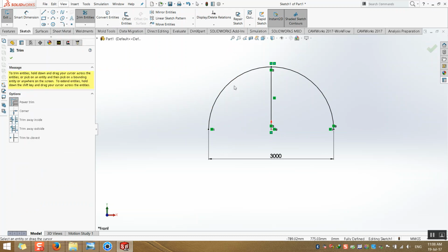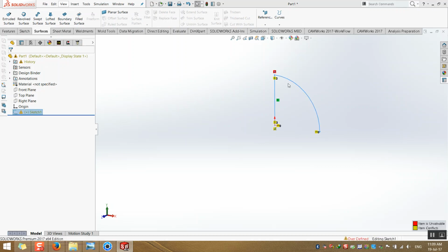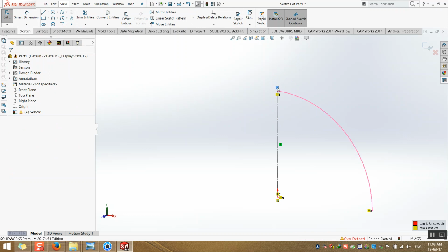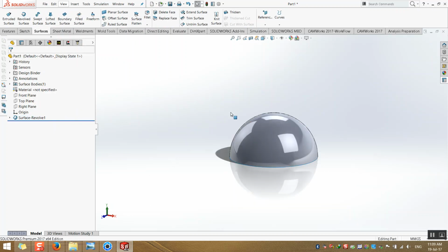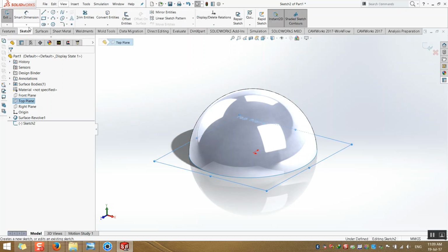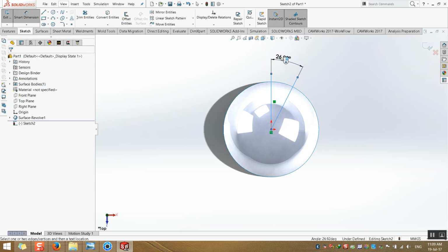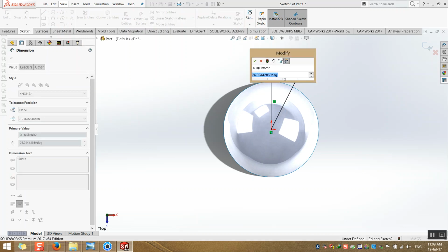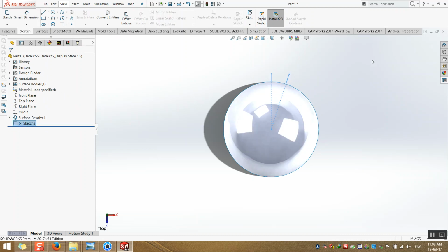Trim. Check. Also can be as a construction file. If you need also to get a specific angle, you can do it here in dimension as an equation, for example 360 divide 20. He automatically will calculate the dimension. Okay, you don't need any external calculator.